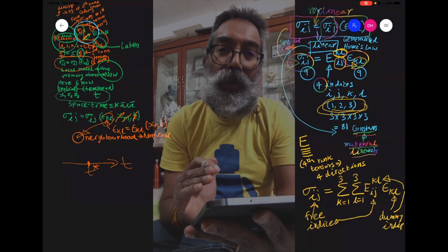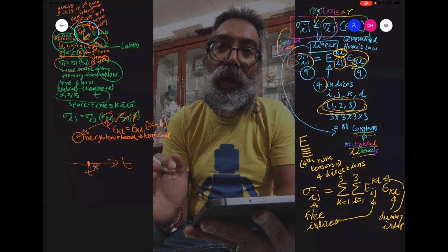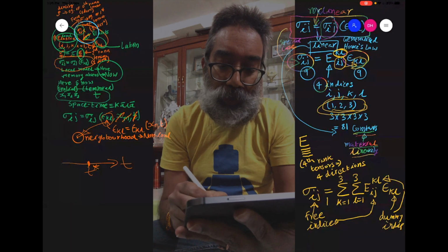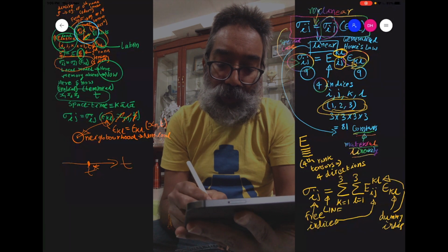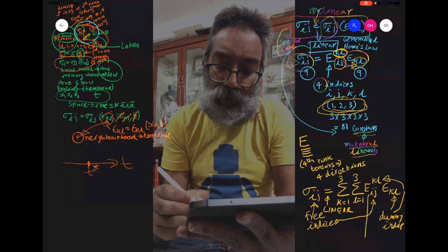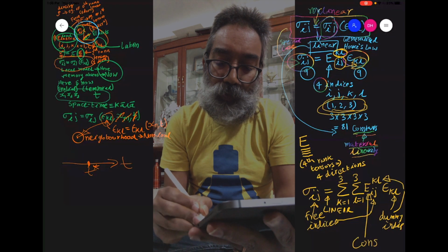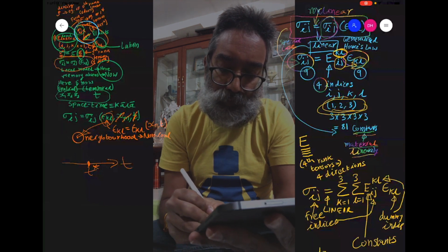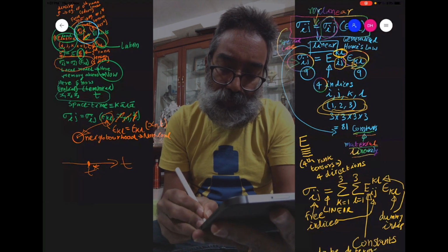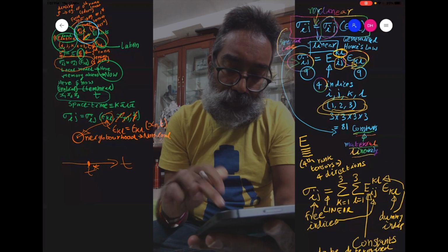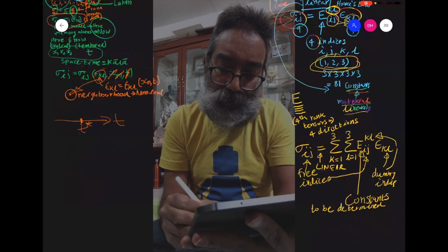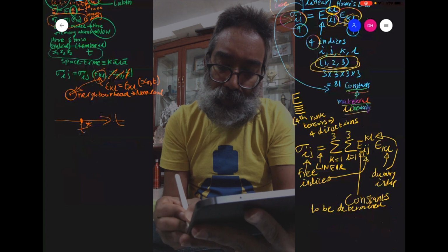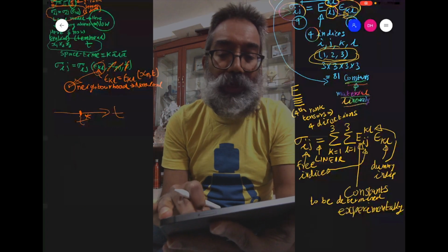So this is the most general form in which linear material elasticity can be put up for the non-local, non-memory case, where you're basically having the stress depending only on the strain, but that dependence now is entirely linear because we are talking of these E's being constants to be determined experimentally. Okay, so this is what linear elastic material means.